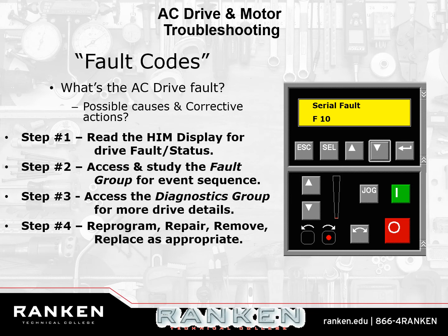Some manufacturers will give you a step-by-step troubleshooting manual for each major fault code. So it'll say like fault 10, and it will tell you to check the incoming voltage. And then if you have good incoming voltage, we'll then check this.